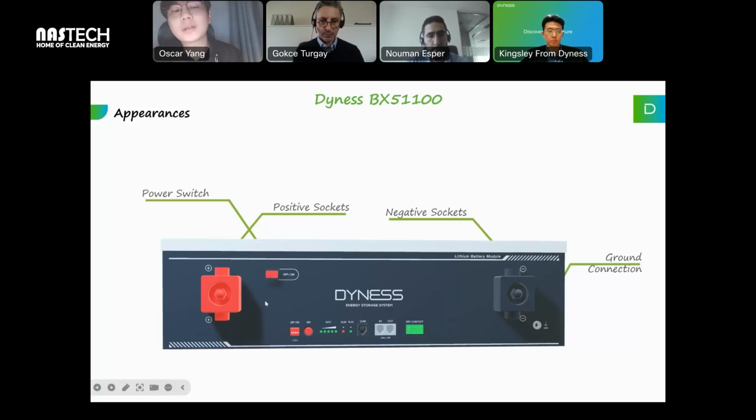The DIP switch is for the battery BMS to communicate with different kinds of inverters at different baud rates. For example, if you want to connect this battery with the DL inverter, you have to set this DIP switch like 0, 0, 1, 0. This is also shown in the user menu. You can check that. For different brands, we have different DIP codes.